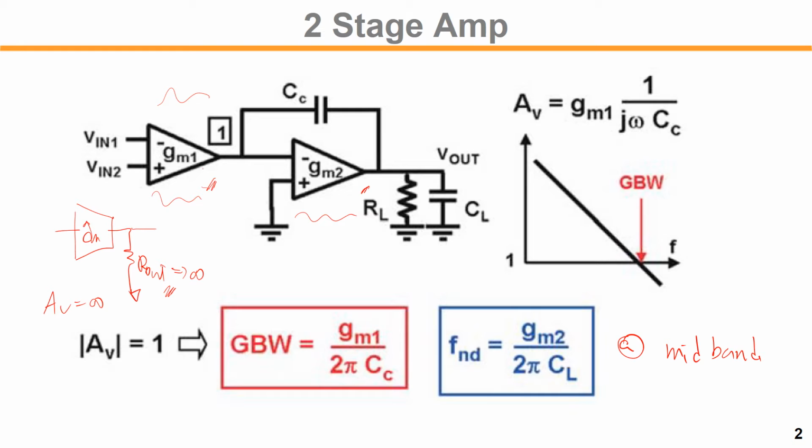Now, what we have is that by inserting a compensation capacitor, without this CC, the problem is we have high output impedance at both nodes, which are closely spaced to each other, so that will create more than one pole, two poles below the unity gain frequency.